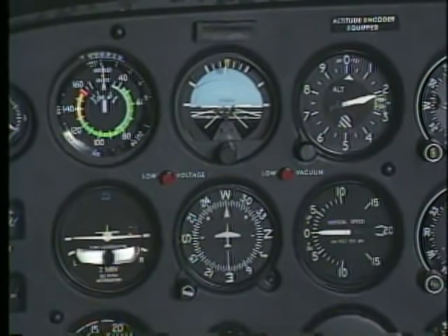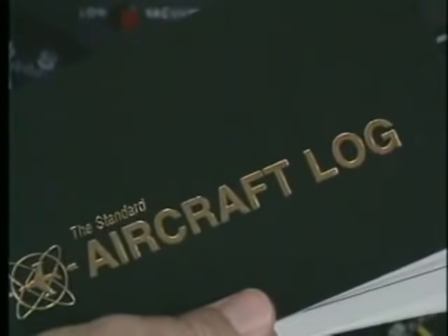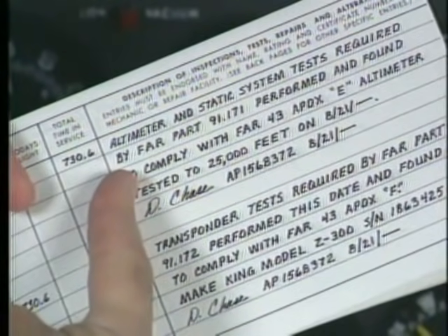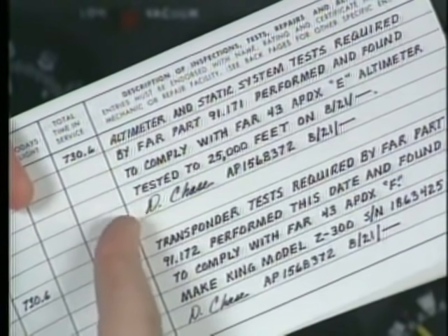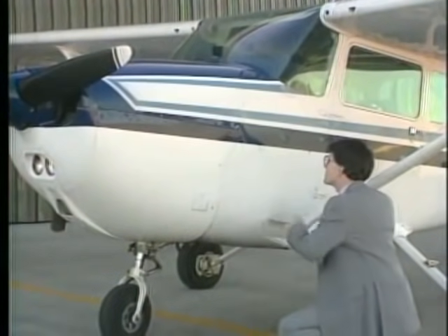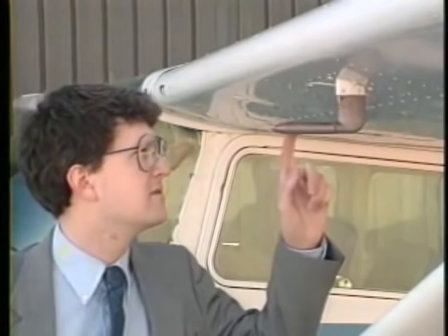Because the flight instruments are so critical during IFR conditions, you should take extra care to ensure they are working properly. This includes making sure the static, altimeter, and automatic pressure altitude reporting systems have been inspected within the preceding 24 calendar months. During the pre-flight, visually inspect the static port and pitot tube for obstructions.